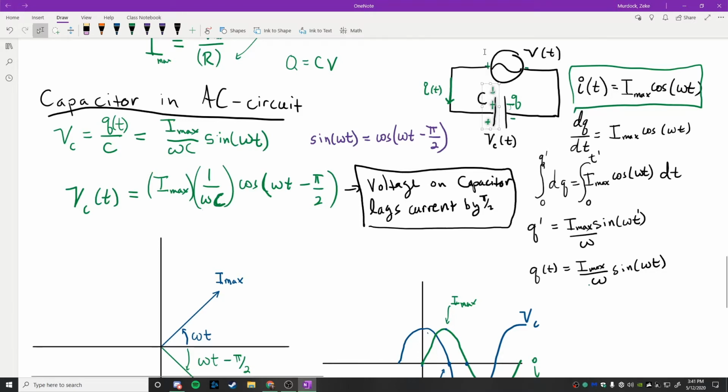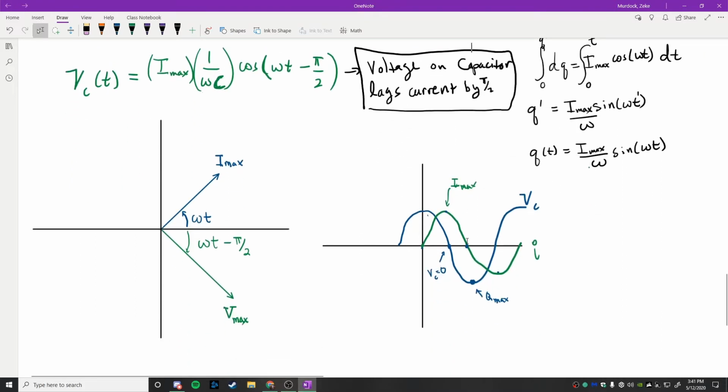So when you have positive here and positive here, you're going to have a breakpoint, right? Where once those charges from this current here flow onto the capacitor, they're now going to want to push back in the opposite direction, right? The capacitor acts, as I said, like a springboard for charges. You push as many charges onto it as you can, but eventually it's going to push back on you. And at some point, there's going to be a balance between the applied current and the voltage that's pushing back from the capacitor. And that's when you get 0 current and maximum charge, right? Now, once these charges have flown out of the system and they've flown back to 0, you get the current flowing back in that opposite direction. Did that answer your question?